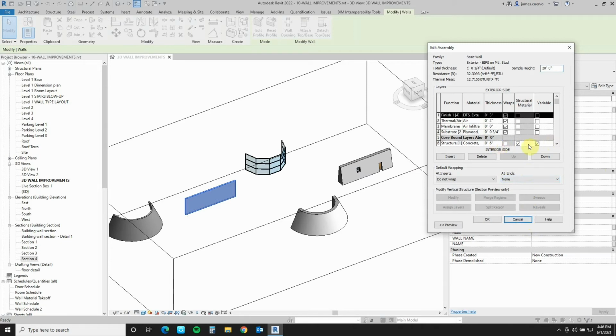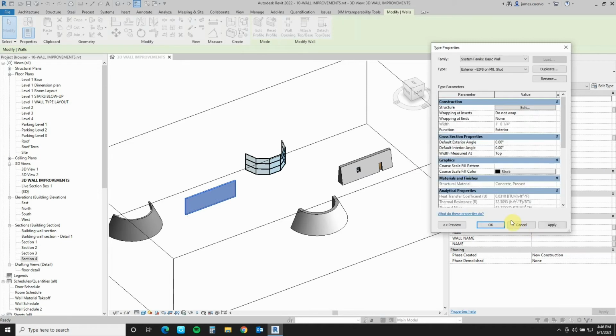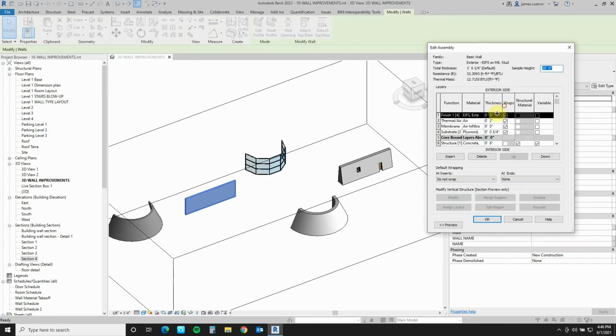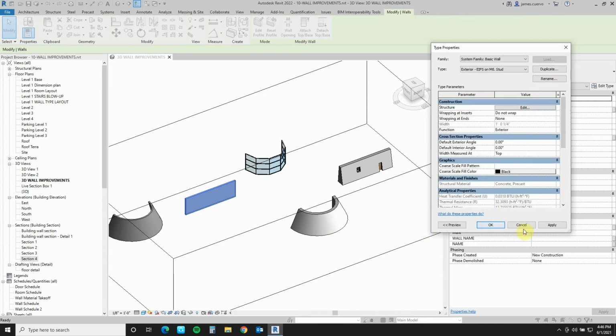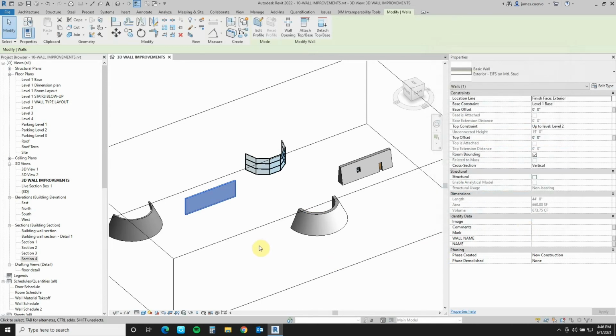Notice that just about everybody's putting it over here in the structural parts. Now, the other thing is that this is also available, and we know that this is not a stacked wall because it doesn't have double finishes at the exterior. Very well. So we know that most walls can be done. Stacked walls cannot be tapered, and storefronts and curtain walls are not tapered.